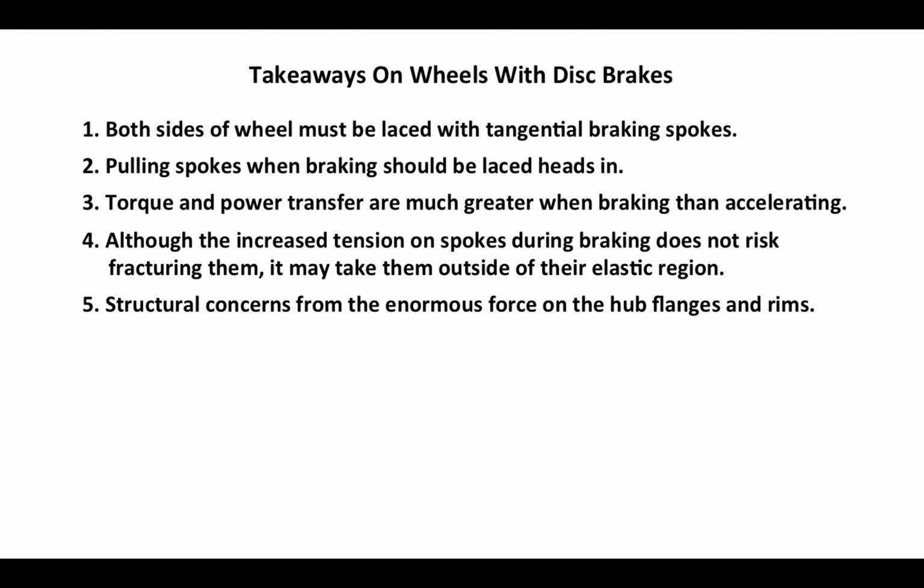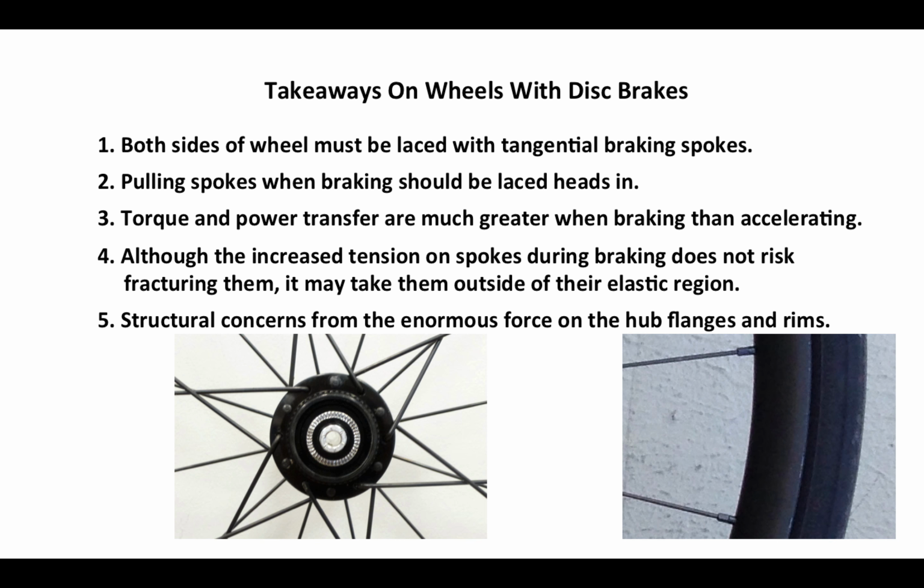And lastly, I would have some structural concerns from the enormous force on the hub flanges and the rims. So in addition to the aforementioned concerns about the spokes themselves, I think I'd start worrying about metal fatigue and the possibility of a spoke either cracking the rim or pulling through the rim, or at the hub, the possibility of a piece of the flange eventually breaking off.